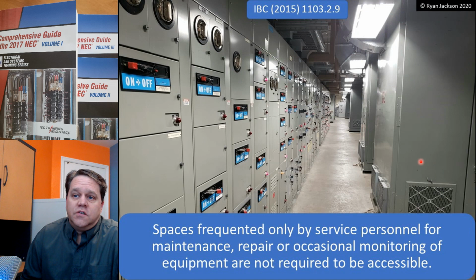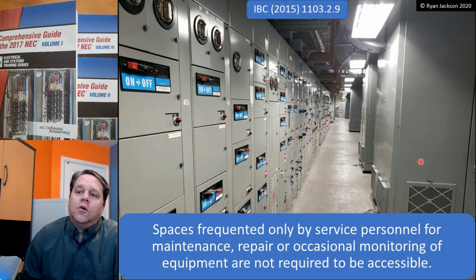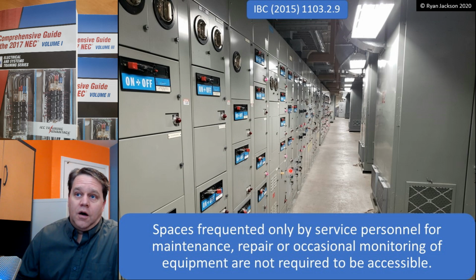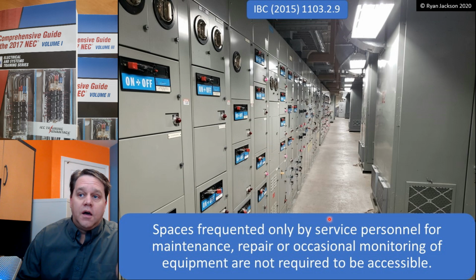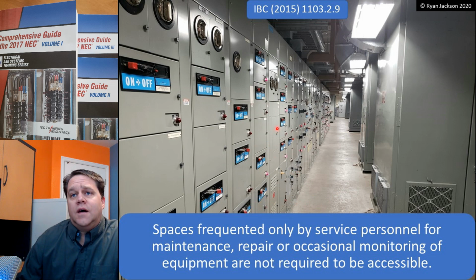One that's important for electricians to understand is spaces frequented only by service personnel for maintenance, repair, or occasional monitoring of equipment are not required to be accessible, and that's a big deal. So here we've got this equipment room. Now, given the nature of this facility, it's probably an employee work area, but even if it wasn't, this would only be utilized by service personnel, electricians, maintenance, repair, things of that nature. So none of this would have to be accessible. It would be pretty tough if the maximum height for all of the equipment in this MCC was 48 and the lowest was 15. It would be next to impossible.